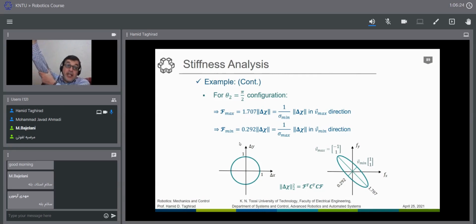You can exert a lot of force on singular configuration without becoming compliant or any movement in the system. And the reason is because the force and the position, the Jacobian in the velocity is in forward direction, but in force in the backward direction. The Jacobian transpose was coming into the picture.